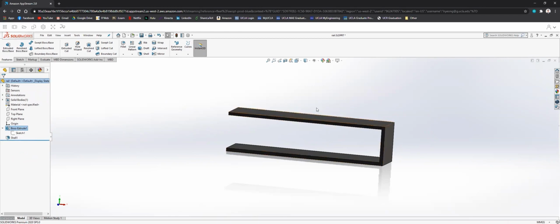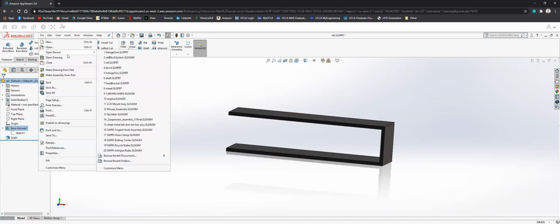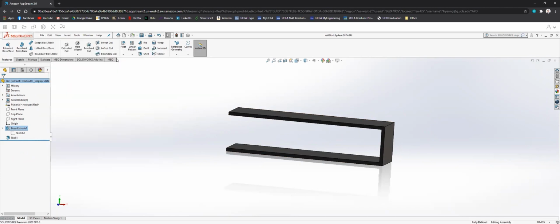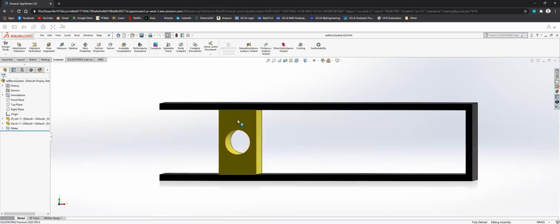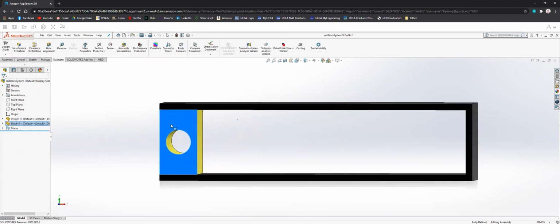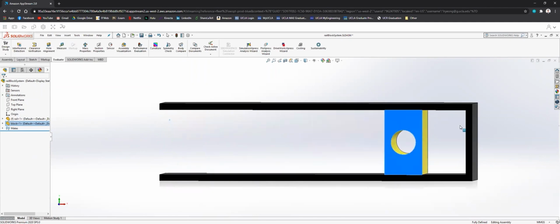For example, if I change this single dimension from 86 to 100 in terms of the length of this rail, I would need to go back to the rail block system. Now you increase your length, but your mating distance, which you set to 72, still stops here. Even though you increase the length, you have to adjust accordingly by changing the mate.